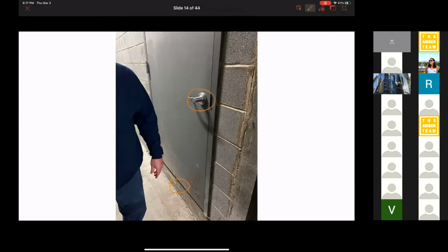Now, in most bigger buildings, which are the type of buildings that would have an indoor transformer, because of fire code, many bigger buildings aren't allowed to, there may be type 1A or type 1B or type 2A, some kind of a less combustible construction type. And as such, if you had a hospital, we wouldn't want flammable oil to be in the basement of the hospital, because if it caught fire, it takes a long time to get people evacuated from a hospital.